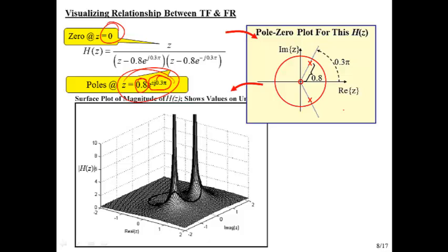And we can imagine these poles taking the z transform, the H of z, up to infinity at those points. That's exactly what those poles do. Now, we can think about walking around the unit circle, starting over here at minus pi and walking around the unit circle and ending at pi. So this is the real axis, this is the imaginary axis.